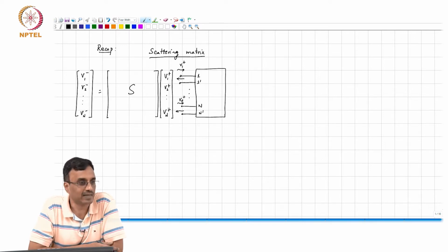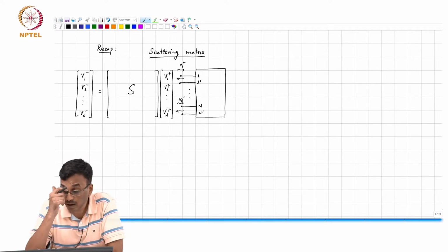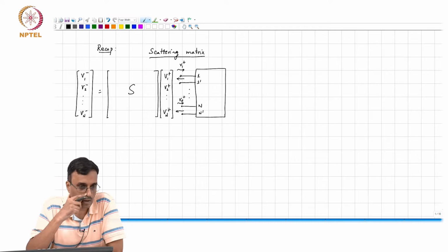A cable is modeled as a transmission line, and if you terminate a transmission line with a short circuit, at the other end of the line you can see an impedance which can go anywhere from being a short circuit to an open circuit to anywhere in between.